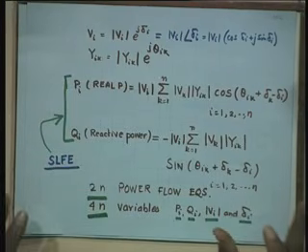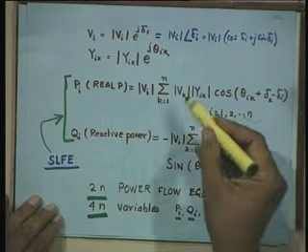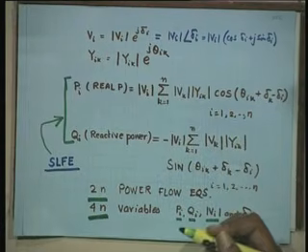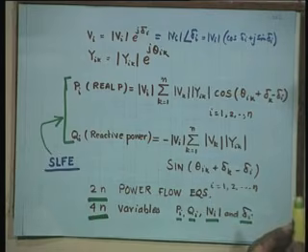That swing equation you have to solve by numerical techniques, the Runge-Kutta method or the modified Euler method or whatever, which you will learn when you read stability somewhere. Here luckily there is no time. So, what is it? It is a set of non-linear algebraic equations. Why non-linear? There is a V squared. The cosine and sine themselves are non-linear. If you expand cosine theta, it is 1 minus theta squared by factorial 2 etcetera, an infinite series. Similarly, sin theta is theta minus theta cubed by factorial 3 and so on.